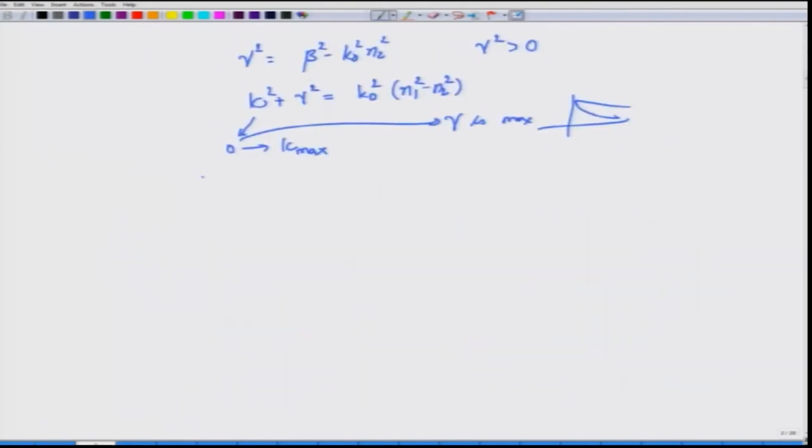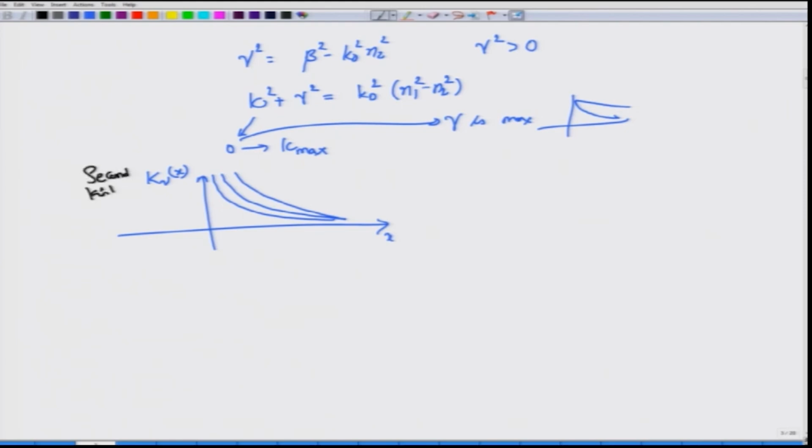The other Bessel function that will be the solutions outside the cladding, which you want anyway because you are looking at evanescent waves, are called the Bessel functions of the second kind. These are the second kind and order nu. Again, the order is nu and I have used k to denote the second kind. Some authors use y, some authors use n. So, these are all different notations, so please do not worry about those.